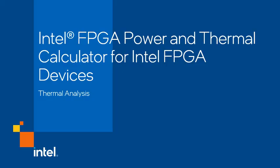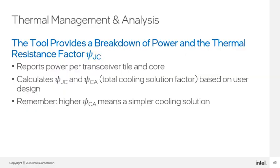For the final section of this training, we'll look at how to set up and perform a thermal analysis using the PTC. As discussed, the PTC can perform a thermal analysis that accounts for the supported device's multi-die architectures, providing a breakdown of power between the transceiver tiles and the core die. The tool calculates psi-JC, the thermal resistance factor, for each die specific to your design. A psi-CA value is also reported as a goal for the design of your cooling solution.